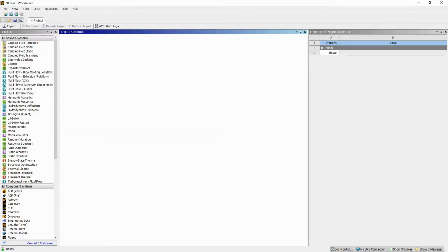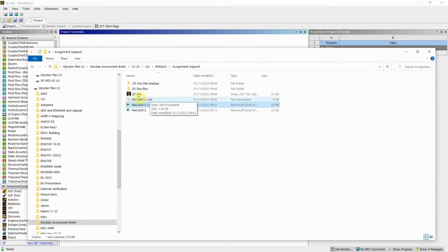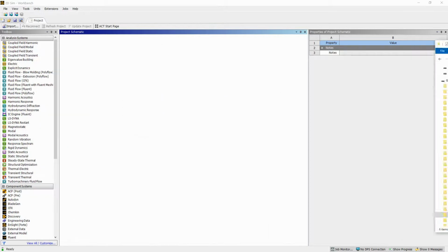And just to show you what happens, in ANSYS, in that working directory, it creates an icon and then a folder. Very important, you don't mess around with the folder, but once you're copying stuff from your desktop, make sure that you grab both elements. Do not put this icon into the folder, they have to be separated. So when you double click on this, it will look for the folder and extract all the information that's needed.